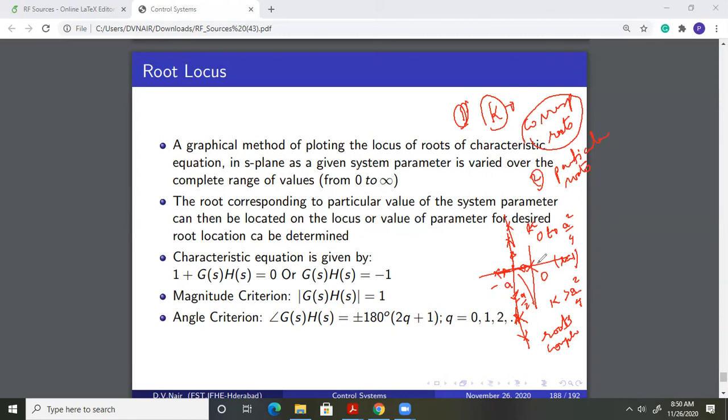So this is something very important, what we can now analyze with the help of an obtained root locus: the range of possible values of k that allows us to keep the system stable. And remember, here when we talk of roots, we talk of the roots of the closed loop system, the closed loop poles. In some cases, you will see that you have a root locus which even moves towards the right half, like we have here something like this. We will see soon.